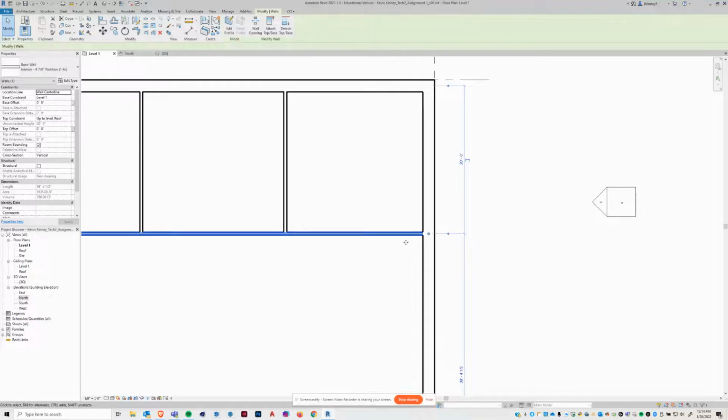Now that's not exactly right because this dimension line is going from the middle of this wall to the middle of this wall. So how do we make sure the interior is 20 feet? See this little button right here, this little dot? If you click on that once, it will move around the wall. So I moved it to where I want it. Now I'm going to click on it again. Now it's out there. Now it's on the middle. Now it's on the inside. Do the same here. Outside, inside. Okay, so the inside dimension is actually this. So I want to change that to 20.